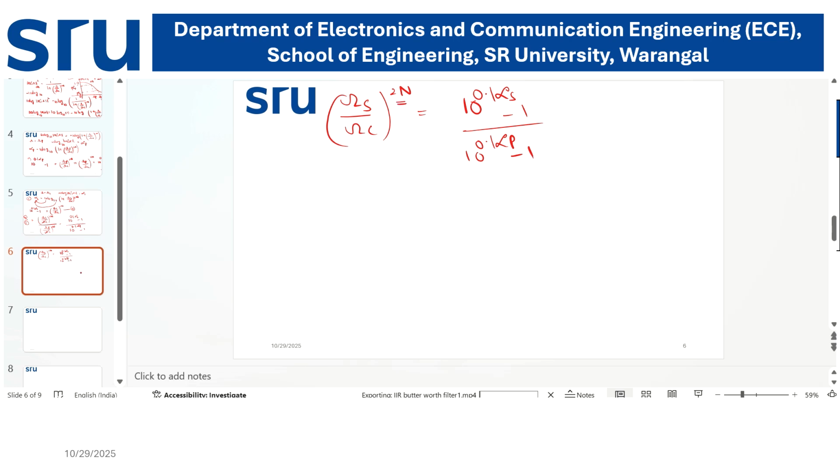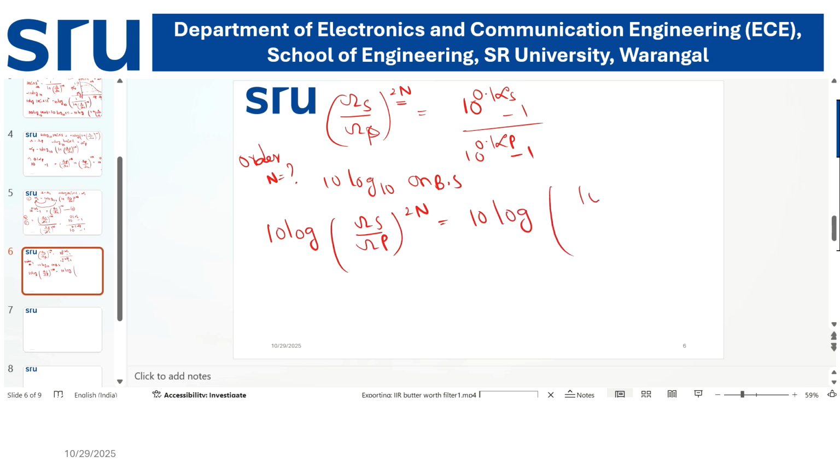Now I have to calculate the order of the filter. So what is the order of the filter? For this purpose I am taking log on both sides. Apply logarithm on both sides. Then 10 log of (omega s by omega p) whole power 2n is equal to 10 log of (10 power 0.1 alpha s minus 1) by (10 power 0.1 alpha p minus 1), the stop band and pass band attenuation.